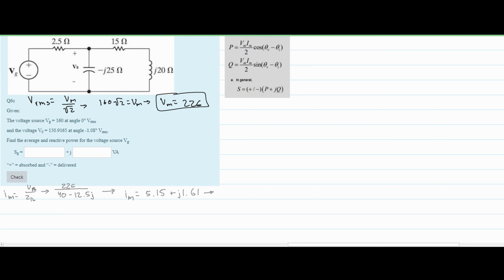In the notes linked below the like button, you can find the conversion. Imax, or if we were finding impedance for that matter, Zmax, is equal to the square root of our real number squared plus the imaginary number squared, and then our angle is equal to tangent inverse of our imaginary number over our real number. And this is going to give us that our Imax is approximately 5.4 with an angle of approximately 17.3 degrees. If we check our angle, the x is the real number, and the imaginary number is on the y-axis, so that means this is the quadrant our degree should be in, which it is. So that checks out, and we found our Imax.